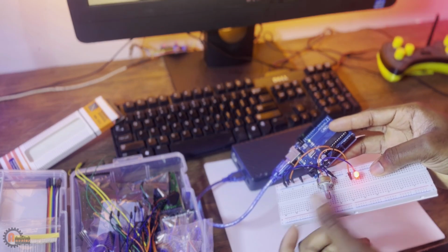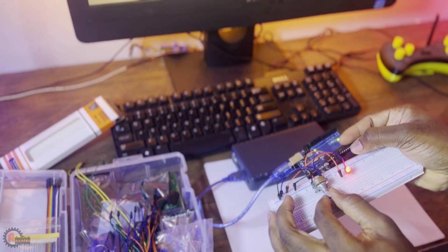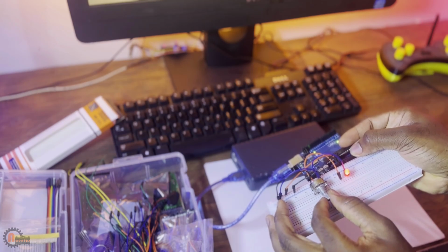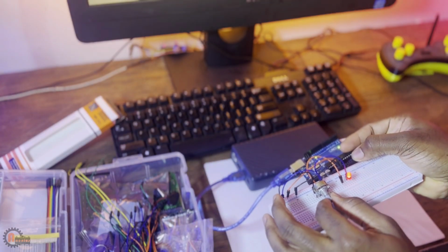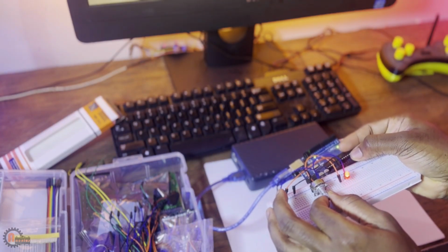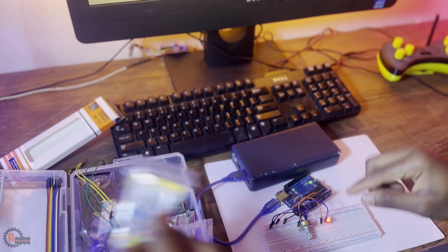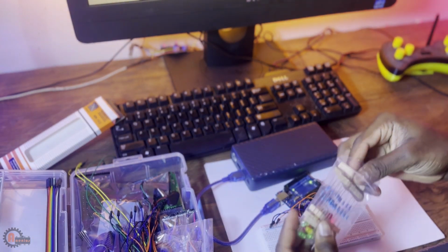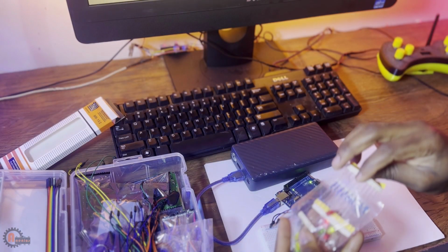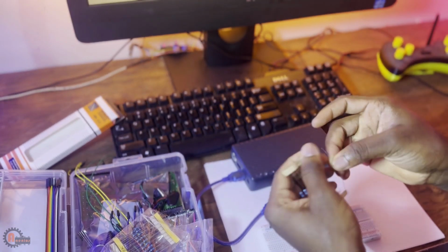Okay, it's bright. Without my resistor, I'm not seeing any trouble here, but it's only a matter of time as the LED is exposed to 5 volts for a long period. It may just tolerate you for a bit. So best practice, you need to put a resistor somewhere between the lines. So let me just grab a very small resistor. Okay, this is 220 ohm.